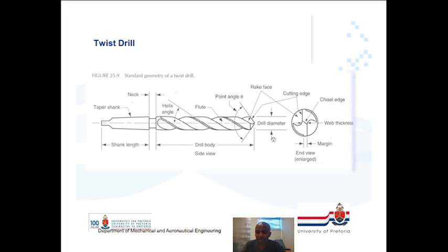Otherwise, the other important factor will be the material properties of the material that you are drilling on. That will also play a major role. So with enough experience, you should know the tricks around drilling, such that when it's this material, you'll be drilling at this speed, and you'll be using this type of drill bit. If you need a cutting fluid or a cooling liquid to cool your drill bit while you are drilling, you will also know this out of experience.